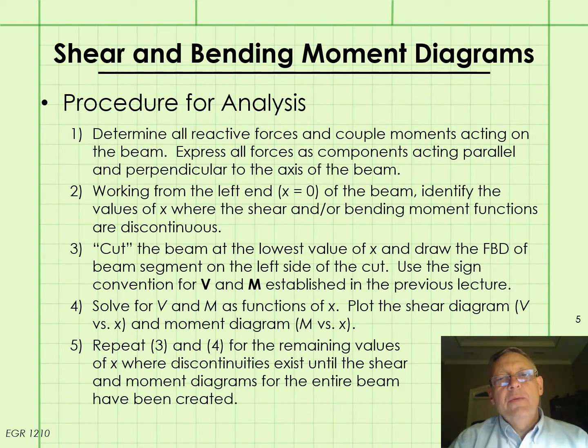Here's the procedure we'll be using to create shear and bending moment diagrams. The first step will be to determine all of the reactive forces, that is the support reactions and couple moments acting on the beam. We then need to express all forces in their component form with those components acting parallel and perpendicular to the axis of the beam.